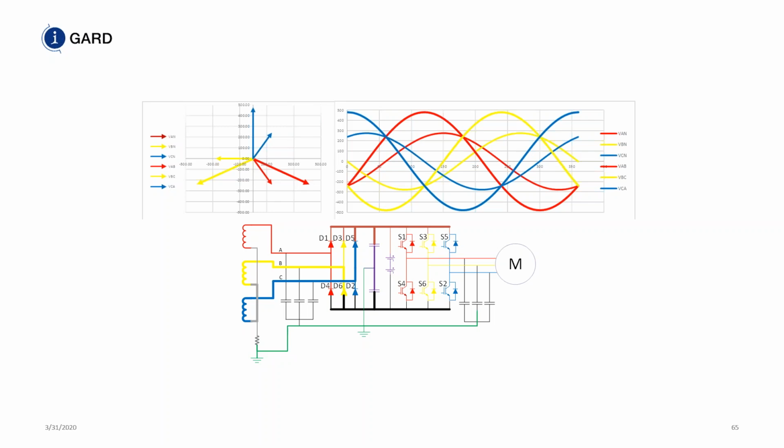How do you determine the charging current? We can do it if you have a cable schedule and load distribution on your system. So we can actually calculate what your charging current is on the system.